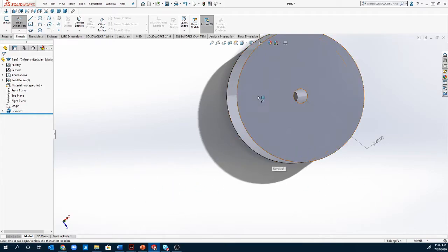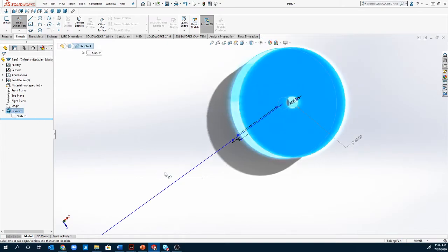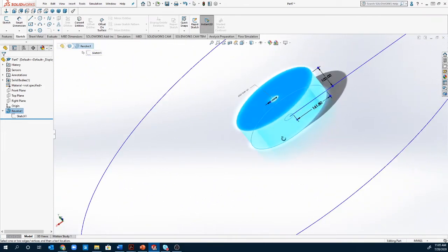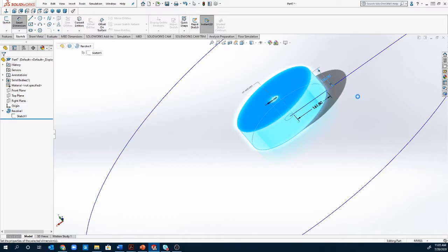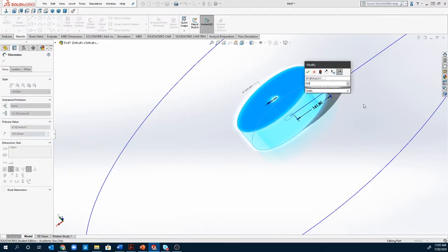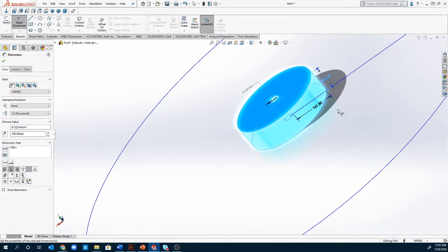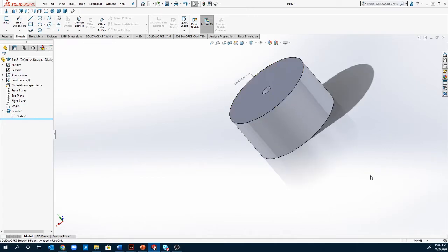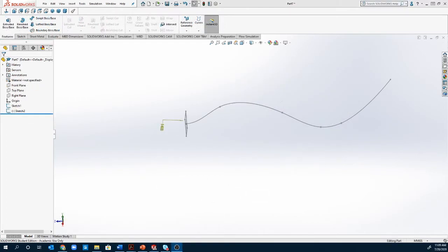Now if you want to change something about it, you can always double click on the object and it's going to show you all the dimensions here. And simply, if I went here instead of 100, change this to say 200, you just click on it, 200, enter, and once you OK the dimension, it is going to ask you to rebuild. You have this little traffic light, you click rebuild, and now it's 200 tall. So you can adjust things without actually editing the object or the sketch.